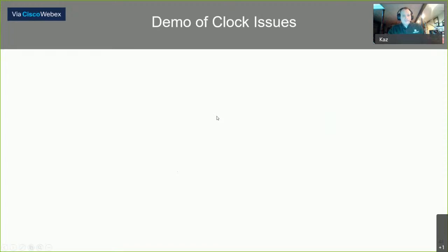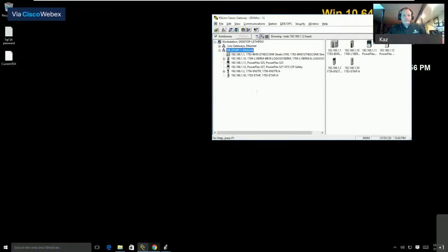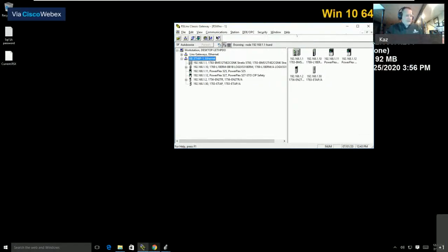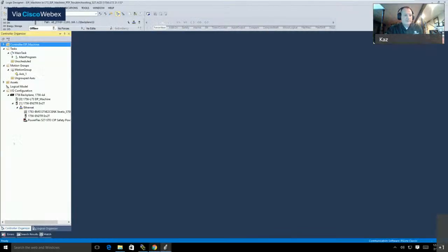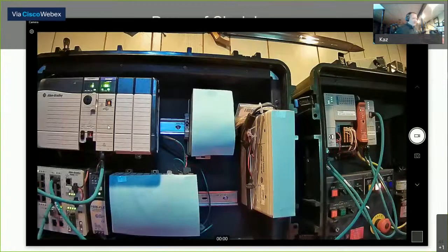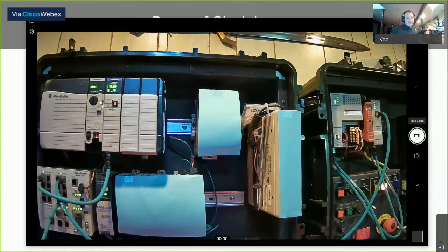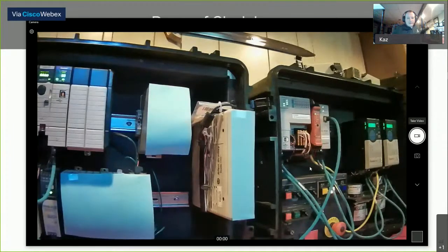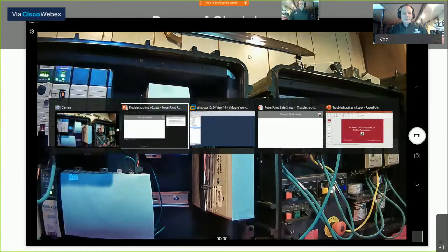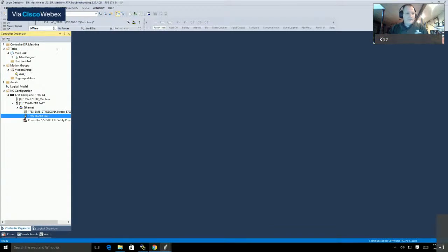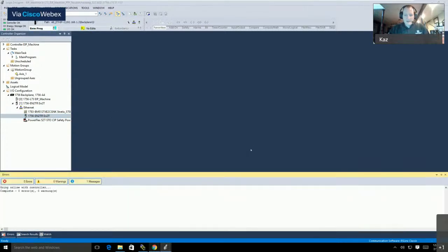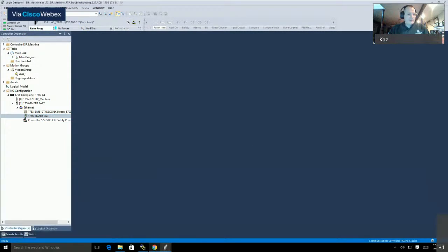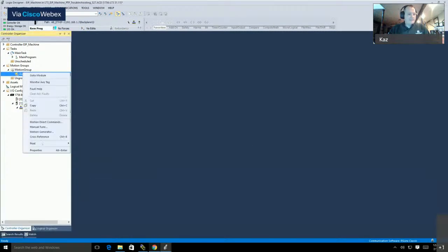So, clock issues. All right, we're getting into the stretch here. I'm going to go look at the camera. Okay, so here's my L73. He's talking to that 527 over there, and let's take a look at what he's looking like in his controller. We're going to go online, and we'll see who his master clock is right now. First of all, let's look at the axis, and we'll look at the properties and see what he's doing.